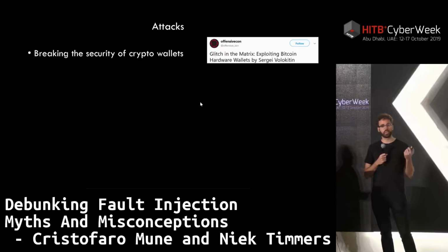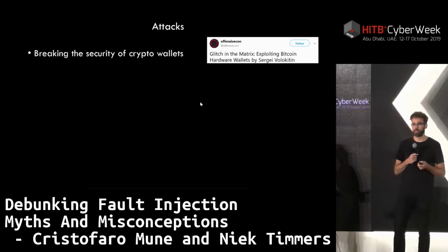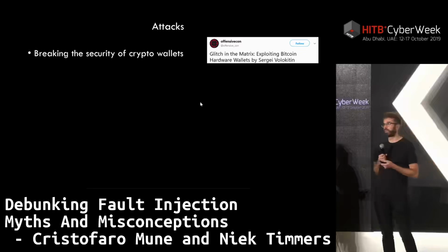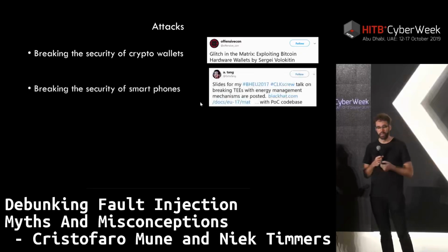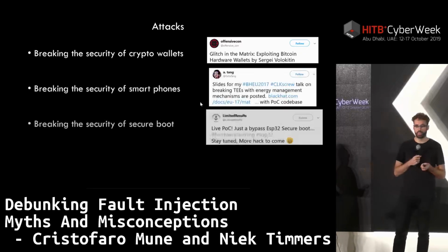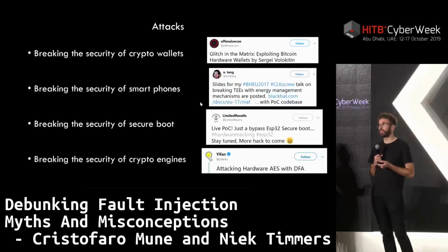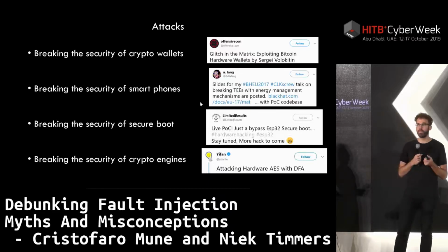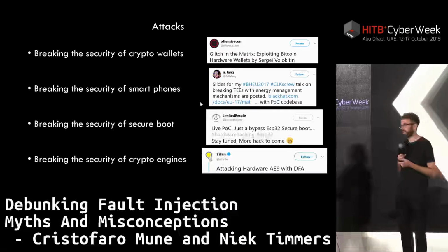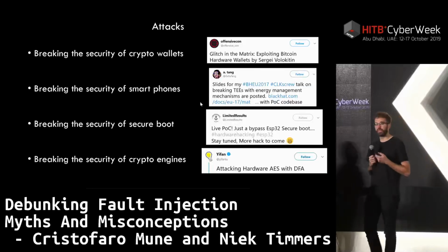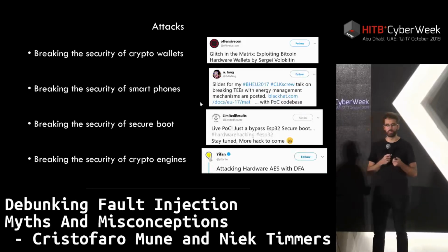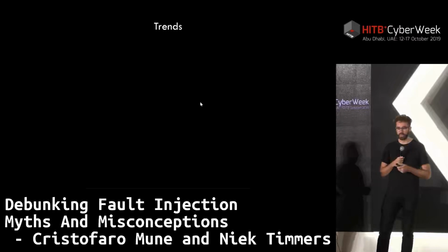And also because there's research being done, there's tooling available, there's all sorts of attacks being conducted. For example, there's attacks on crypto wallets, there's attacks on smartphones, there's attacks on secure boot, and there's even attacks on hardware cryptographic engines. And this shows that fault injection is a very versatile tool that can be used to mount all sorts of different attacks. So we will dive a little bit into these things in the remainder of this presentation as well.